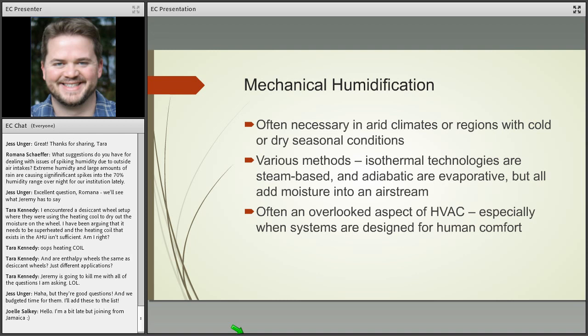And one of the things that really does come up is we will see a lot of systems, and this gets into older systems and, shall we say, non-specific cultural heritage applications. We get into a lot of scenarios where systems will be capable of a little bit of dehumidification. It's not really what they're designed to do, but they're doing enough. It's like taking your window air conditioner and recognizing that you do dehumidify with it, even though that's not really what it's meant for. So that can happen even by accident. But when we're thinking about humidification, it doesn't happen unless the equipment is there in the system. There's no other means of doing this, half-heartedly or to a very little degree. You have to have the humidifier there in the system design.